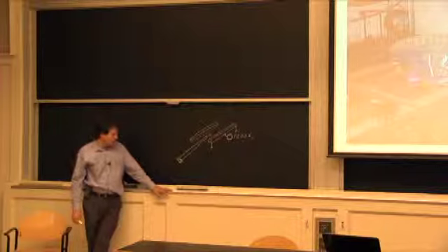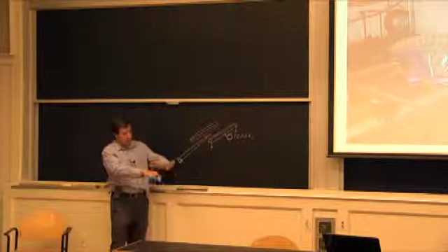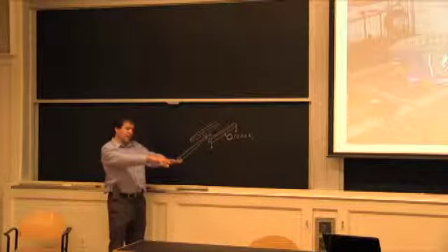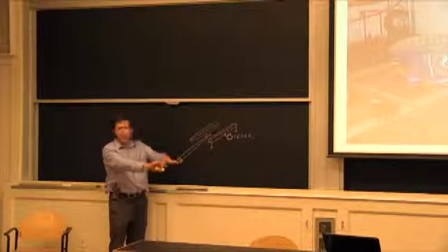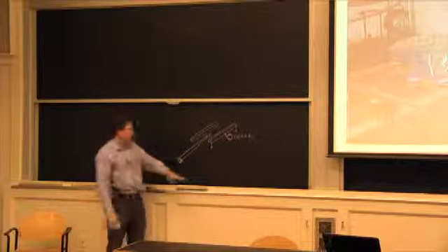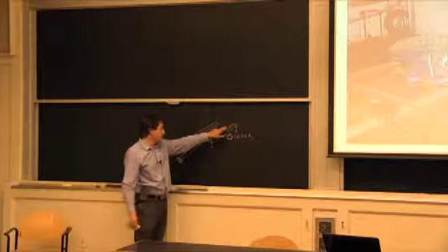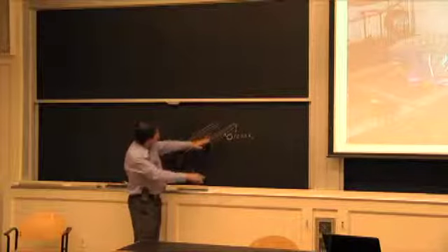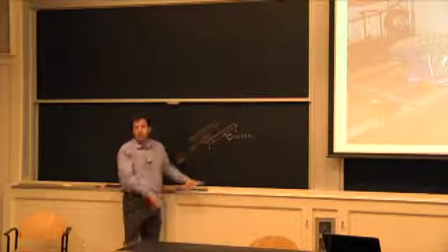But in practice, when I go through puddles and into the field, it's going to have to resist also some torsion. So if I have more weight in that corner, this is going to bounce, and the plane of the trailer will try to rack.